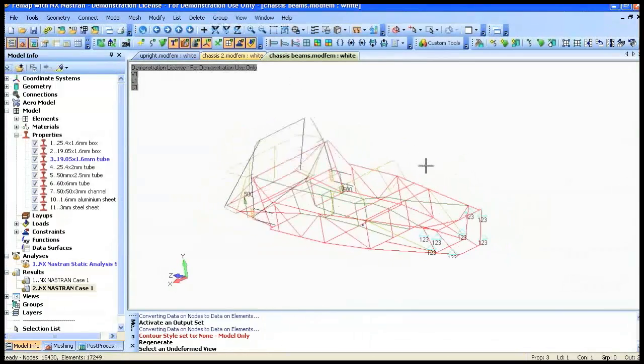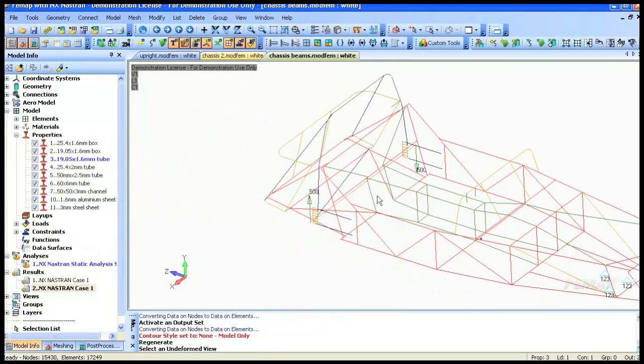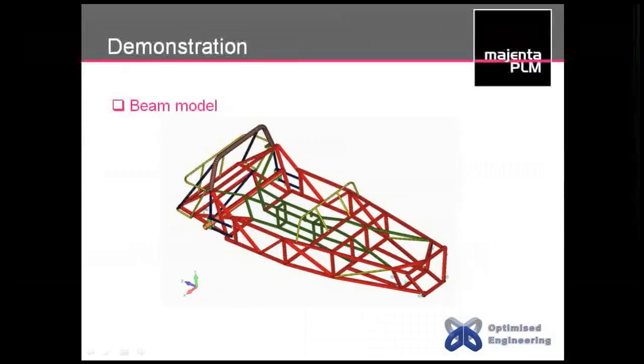Okay, so just a very brief demonstration on how we build a model with beam elements, or how we can, in this case, modify a model with beam elements, run through it, and then look at stresses through sections or global results such as displacements or whatever. And what we're doing with the two displacements at these locations is through some very simple trigonometry. We can just calculate the angle. Because we know the torque applied to it and the angle, we can effectively get the chassis stiffness from that. Okay, so I'll just hand back to Henry to run through the last couple of slides.